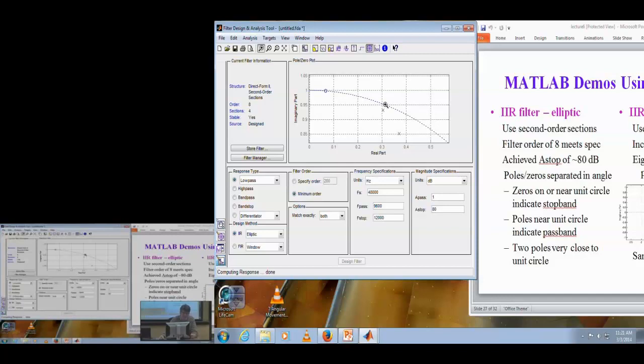So when the pole gets really, really close to the unit circle, that distance gets really, really small, and the magnitude gets really, really big. And if the pole is on the unit circle, it's no longer BIBO stable. I have an oscillator. And if the pole is outside the unit circle, it is BIBO unstable, and it also blows up. If it's on the unit circle, it's BIBO unstable and oscillates in terms of the impulse response.